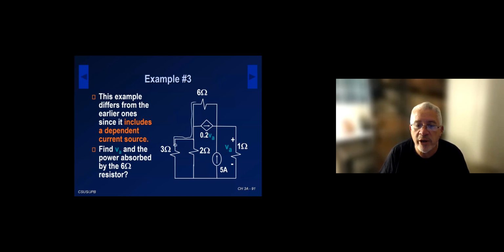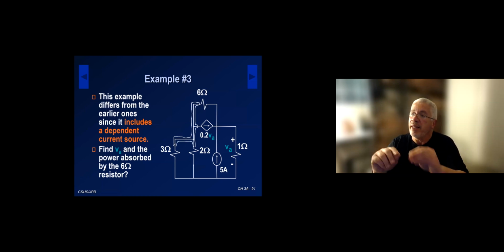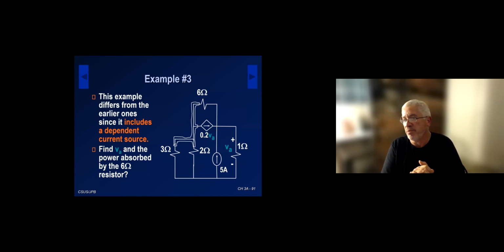As long as we're on a wire, until we touch an element, we have the same node. Right there is the same node, right there is the same node. I haven't crossed any element, so that's one node. Again, I suggest you take your pencil and just trace. As long as you're on a wire, and not crossing an element, you have the same node.